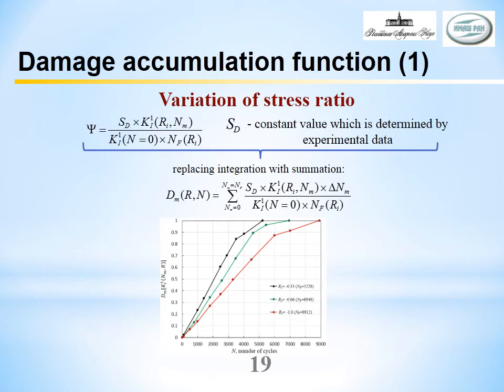Up to these points, damage accumulation occurs according to linear law, regardless of magnitude. The starting point of the nonlinear sections is identical for all three investigated values. It can be assumed that this stage of damage accumulation process corresponds to the formation of macro defects with the subsequent origin of crack and its further spread.